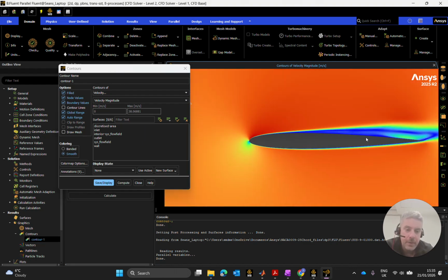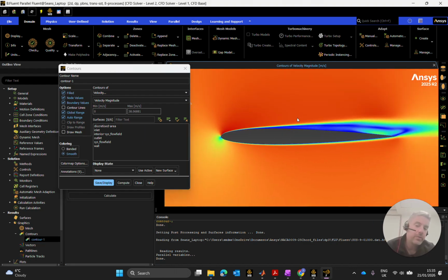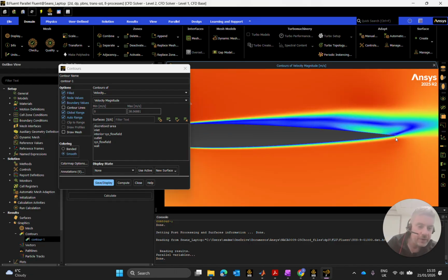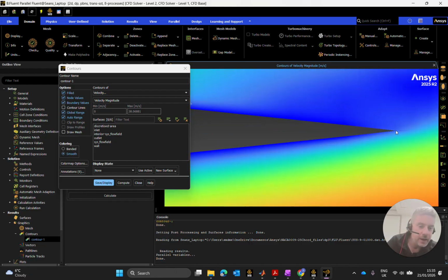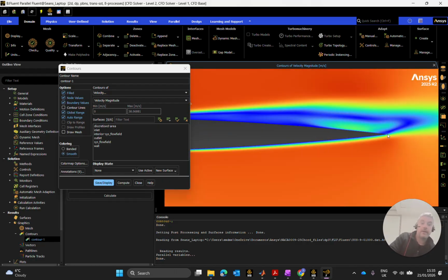But what's happening now is that the air moving over the airfoil is scooting past a little bit too quick to give this time for the separation bubbles to come back. So have a look here, still stuck to the back of the airfoil. Now the other thing in this here is that we have a very pointy trailing edge. Our aft point is a point, which isn't great.